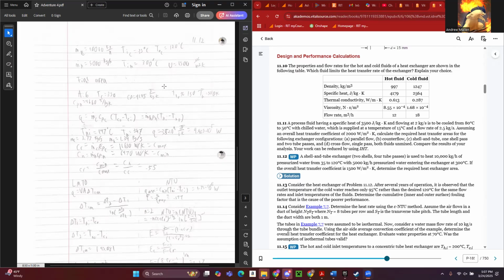And then for the warm flow, I decided to assume a temperature of 150 degrees C, which would give us an average of 500 Kelvin and a specific heat of 4,660 joules per kilogram Kelvin. Why I had to assume, I'll go over that in a second.